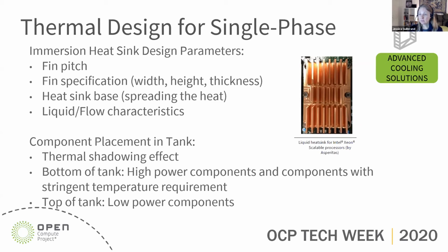When you have a thermally stratified flow, with cold liquid in the bottom and hotter on top, you want the high power components, or the components with the most stringent temperature requirements, to be in the bottom of the tank where you have the cold liquid, while the low power components, or the components with less stringent temperature requirements, can be in the top. So those are the thermal design considerations for single phase.